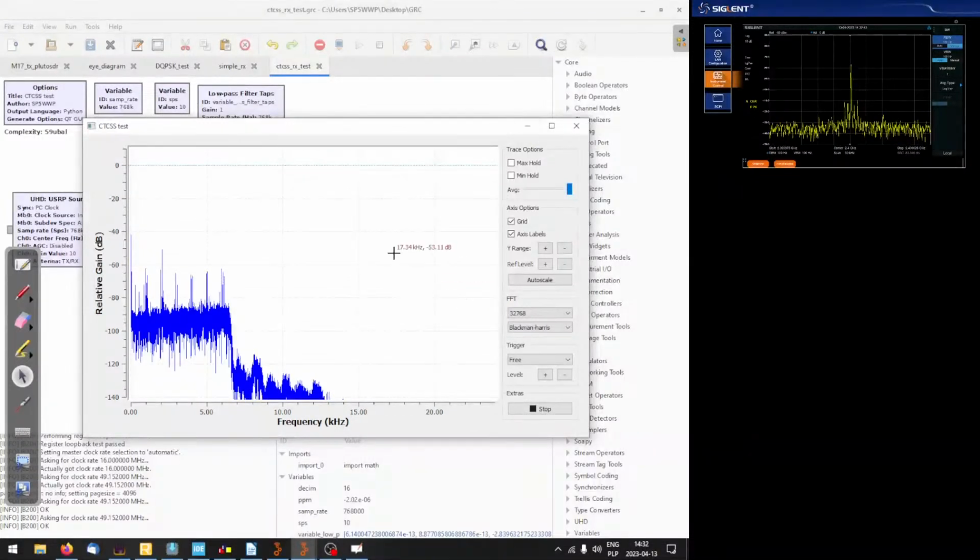Okay, so right now we've got the frequency modulator running in the OpenHT, and the input to the ADC is just half of the supply voltage for the ADC of the STM32. And that, of course, corresponds to a carrier wave, just a continuous wave at the mid-range for the frequency range of the NCO.